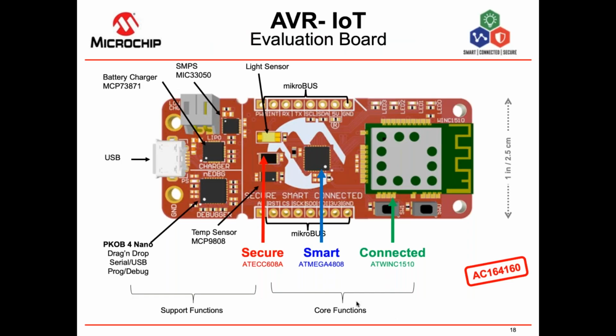So there was a long intro, but now I'll show you practically how this is done in hardware, in a real design, in a real cost-effective, simple, very easy to use, rapid development design. So this is a board that we developed with Google, together with the IoT Core team in Google. And we developed it with them to really exemplify this philosophy. So you see on the right side, that's the WINC, that's the network controller. Right? So it's a Wi-Fi radio, but it also has already all the TCP/IP connectivity.